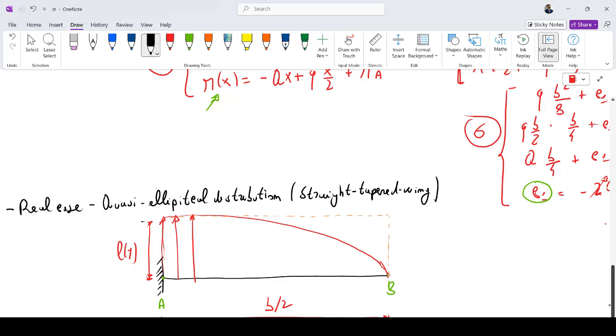But in a wing we have a quasi-elliptical distribution that is not linear. We can see, I hope, this dashed line that is the uniform load along the beam, and it is not so linear, because if I make a line here, in this way, I miss this area.